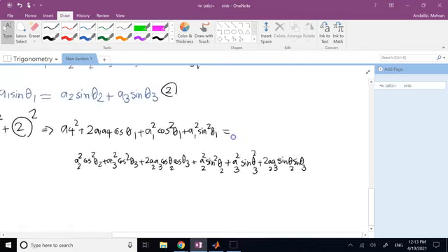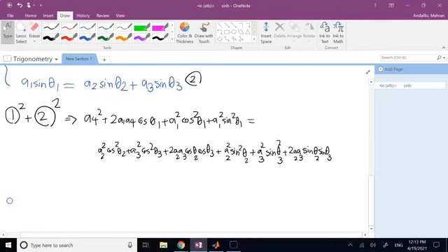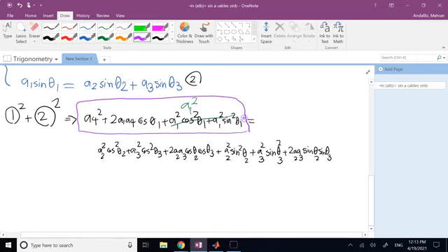Okay, so now it looks like a big mess. But the thing is, all of this left-hand side is known value because you know theta 1 and theta 4, correct? And if you want, you can even add these two together, and this is simply a1 squared. So now, what I would do to get a little better with my notations, I would call this whole thing, I give it some name. For example, I can call it parameter A, which you can calculate when theta 1 is given.